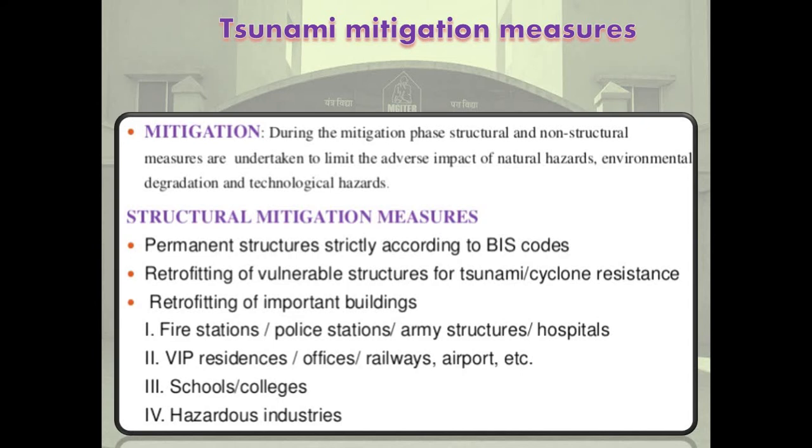At construction sites also, we can use different ways to reduce tsunami problems. Providing stationary platforms in the backwaters for evacuating the public during tsunami, creation of sandy dams at close intervals all along the coast, vertical evacuation structures in all harbors, construction of inland dikes to safeguard vital installations. Okay.